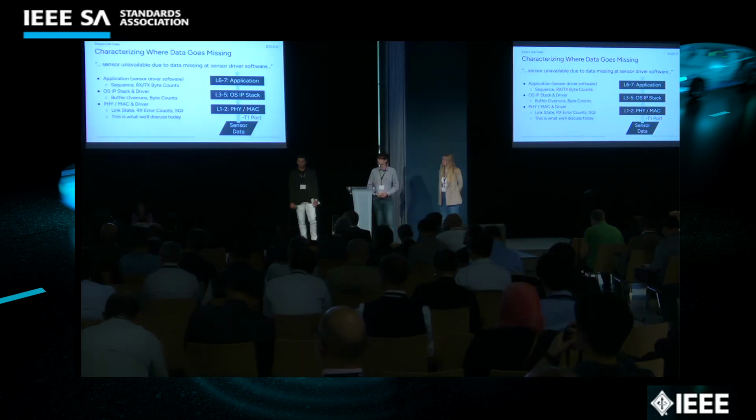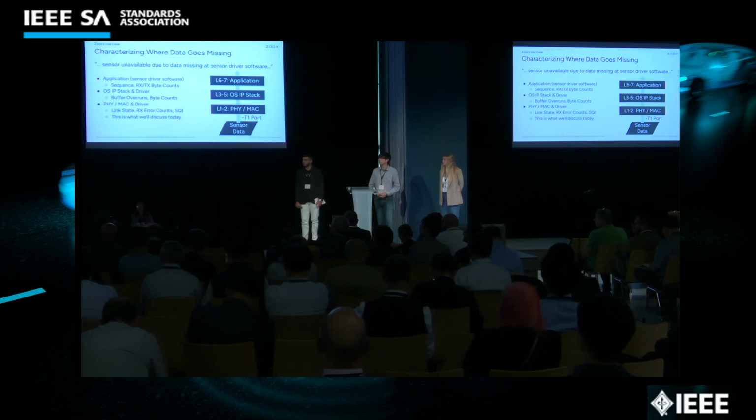And do you also plan to roll this type of mechanism out to 10BASE-T1S, for example? Because there you have a multi-drop bus, and you may see even other things you don't see here yet. Yeah, this is fair. This one is mostly talking about these 100 and 1000BASE-T1, and we do have other physical layers in the vehicle, and generally, yes, we wish to have a similar layer of diagnostics for all of the different physical layers. Yeah. I'm waiting for 10BASE-T1. I've got some years to go to implement it. Perfect. Thanks.